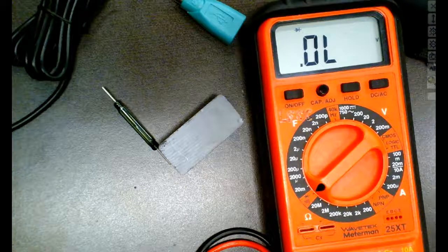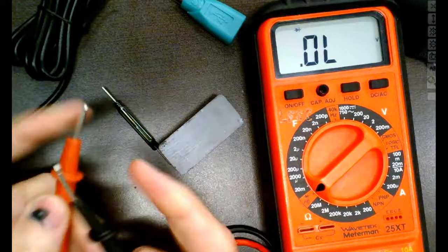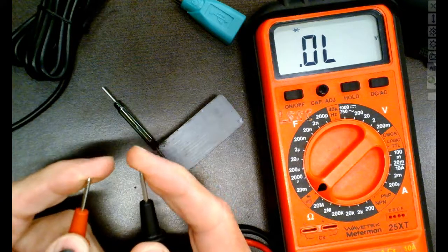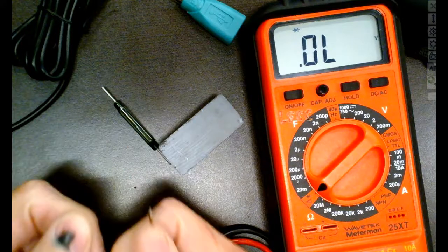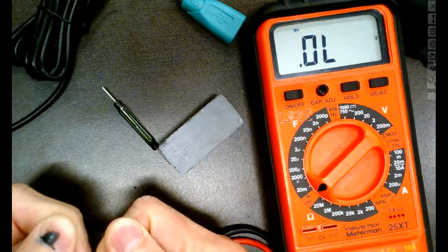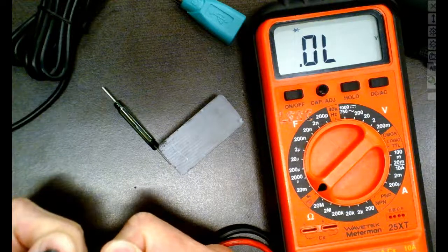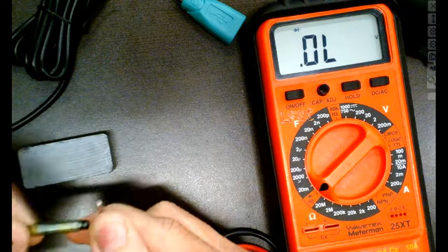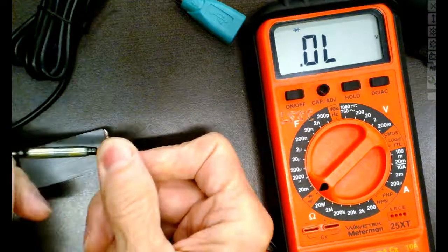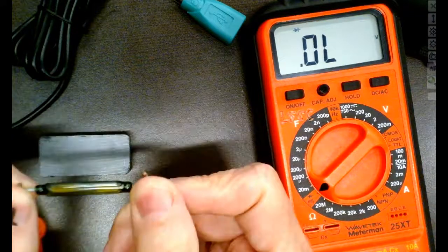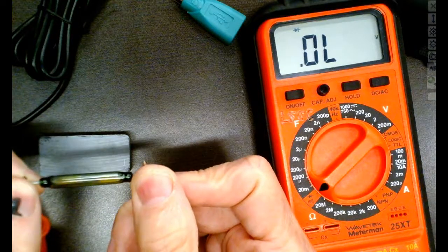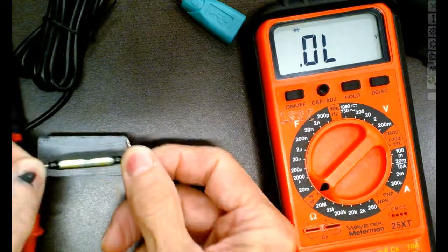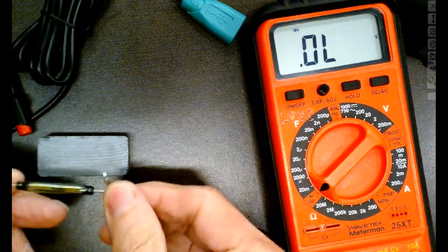We use these to trace wires all the time. We use them to check fuses, circuit breakers. So instead of me trying to look at the meter all the time, I can put a fuse across there. If it beeps, it's good. If it doesn't beep, it's bad. So we do that all the time, and I don't have to look at the meter. So right now, if this works, guys, we have what we call an open, right? And then over here we have continuity. Y'all hear it work?